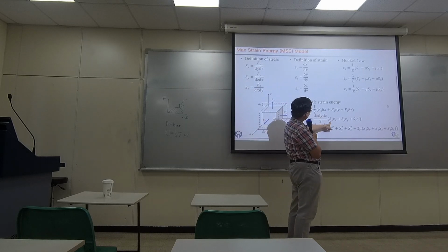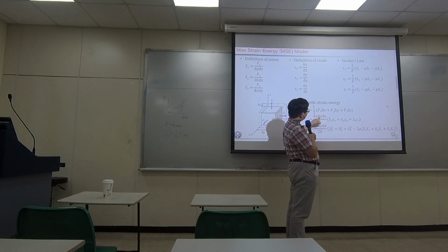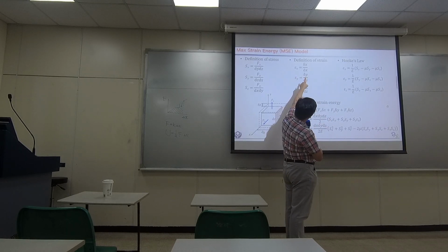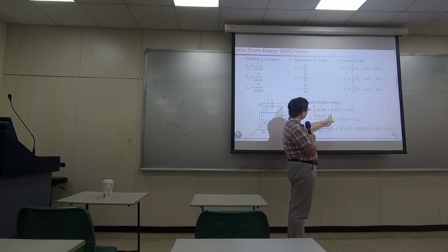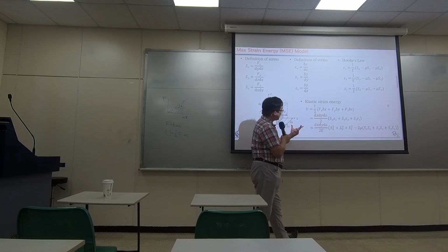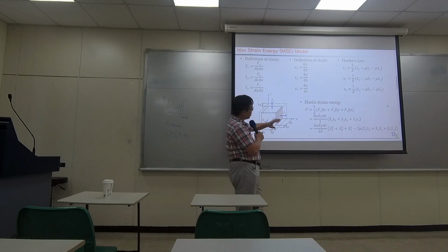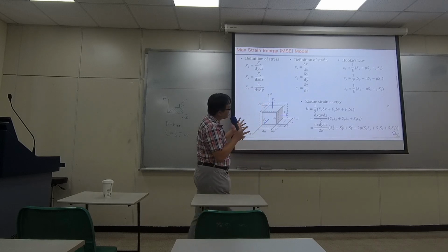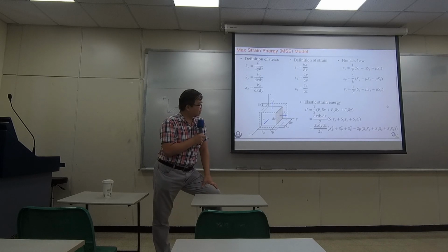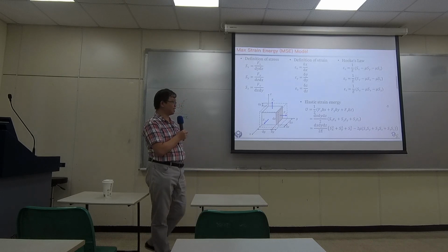So you do have a sigma x times dy and dz right here, these three terms. Now your delta equals your strain times dx. So overall, you always have a dx dy dz right inside the bracket, so you can take them out. And inside the bracket, you realize you do have sigma x epsilon x plus sigma y epsilon y plus sigma z epsilon z.